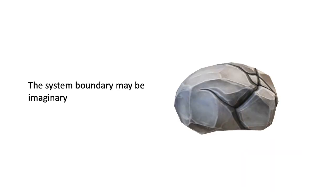Now, the system boundary may move, so if the rock falls, the system boundary moves along with it. The system boundary can be a purely imaginary one. For example, we can select an infinitesimally small volume of the rock and define that as our system. We will be doing this quite frequently, and then we can do a mass or energy balance on this small volume and integrate it over the entire volume of the system.